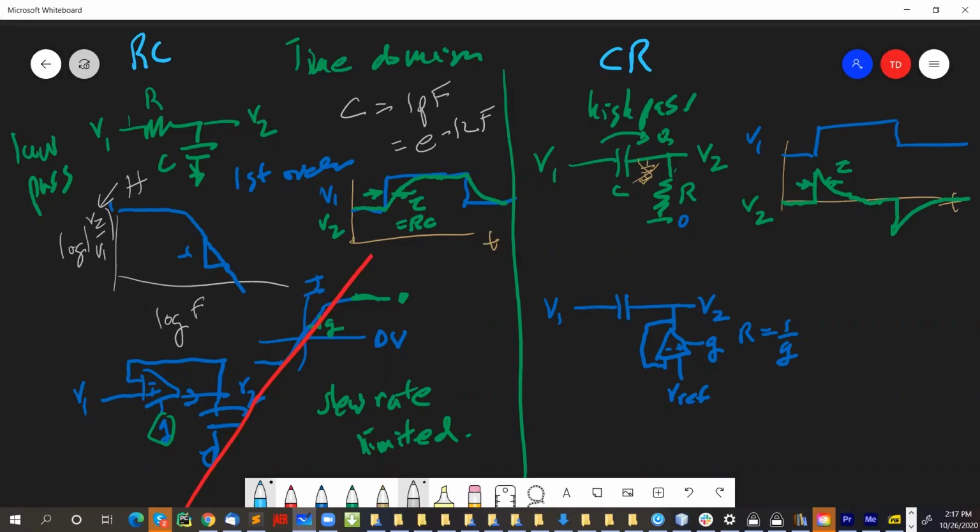And you're going to set the current of this transconductance amplifier so that you get a particular conductance or equivalent resistance to give you a time constant tau, which is in the range that you need in order to sample it using the analog to digital converter. So you're going to compute the bias current on the amplifier such that you end up with a time constant that's in a reasonable range. And then you're going to see whether if you actually set that bias current, you get the time constant and behavior that you expect. So that's the mission.